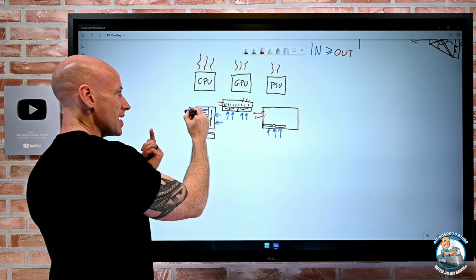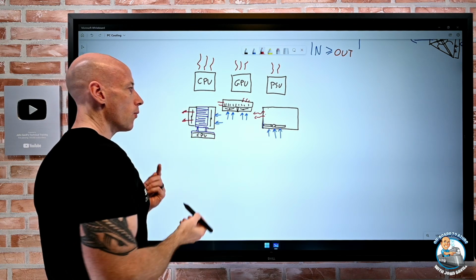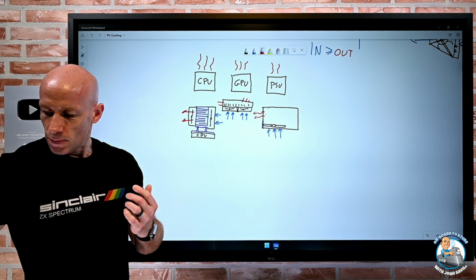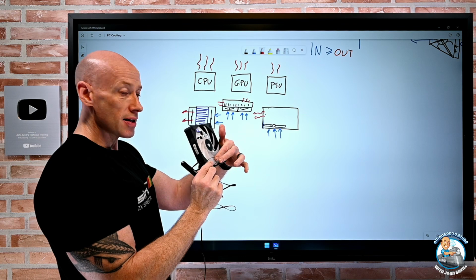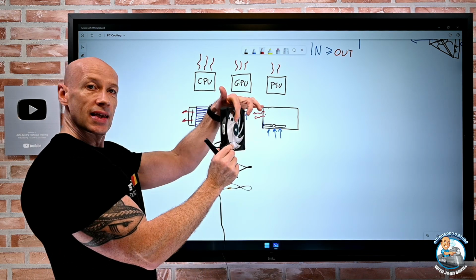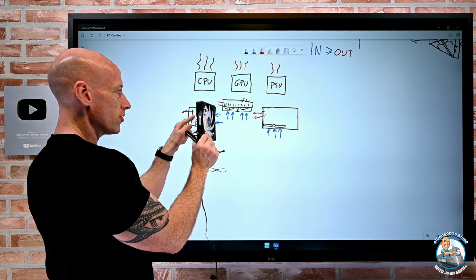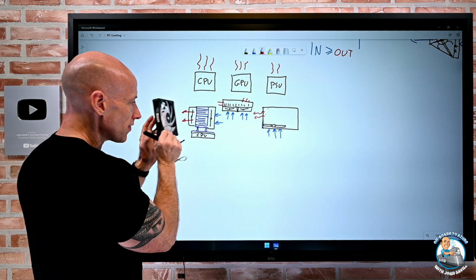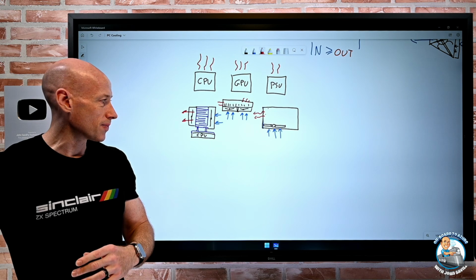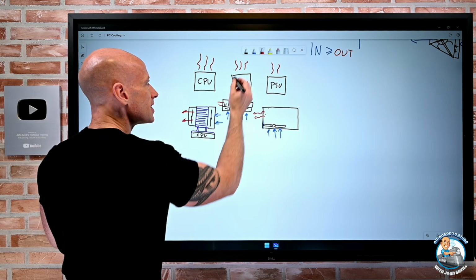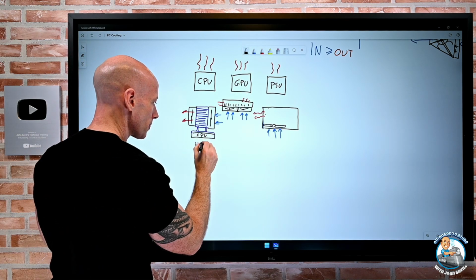So now this takes the heat and it blows it out that way. So the orientation of my fans would be the same way. In this case, this side, remember this is intake, it'll be facing that way. And then on this side, it would be facing that way as well. So they're facing the same direction, so I get the heat flow going through those. So this is the heatsink and fan combination.